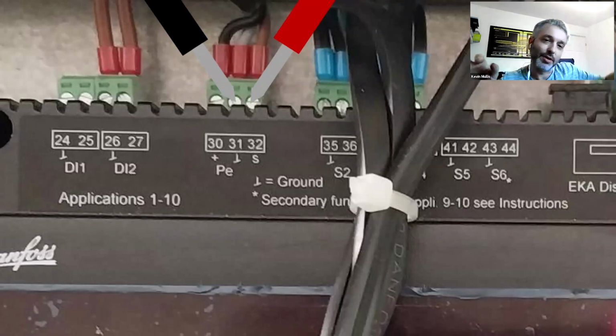Now, Danfoss is very good with transducers. You can use one transducer to run a whole island of cabinets. That's great, it saves you a lot of transducers. You don't need 6 transducers if you've got 6 cabinets on an island. The pressure is going to be close enough, especially on CO2, on all those cases. And Danfoss lets you daisy chain all of that together, so your 5 volts get linked up, your grounds get linked up, your signals get linked up, and you will get the same reading on each controller.